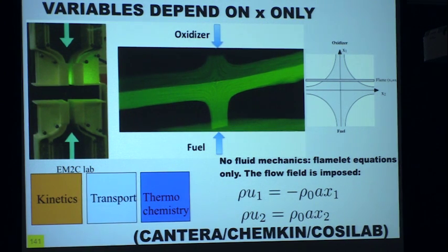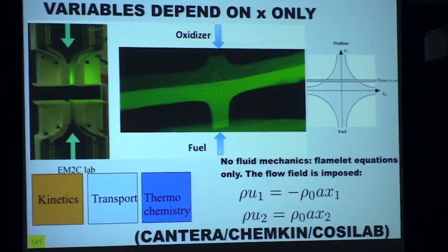So those of you who are working on flames probably know that the most difficult thing to do when you want to compute a 1D laminar flame like this one here, a stagnation point flame, is to get the first solution, to be able to converge this thing, because you typically have 1,000 species, you need to find an initial guess for them, and usually if you don't find the right guess, it just explodes. So it's a very difficult game here. This is why we need to simplify the chemistry. But still, this is a very simple flame, okay?